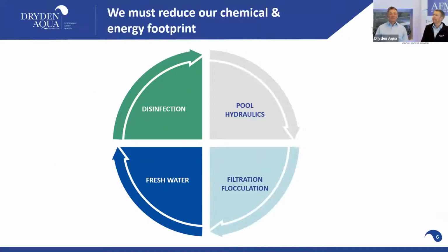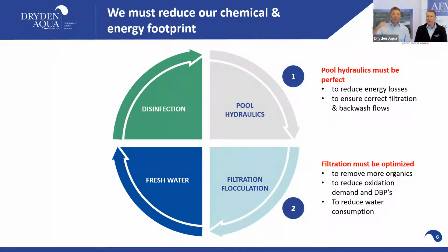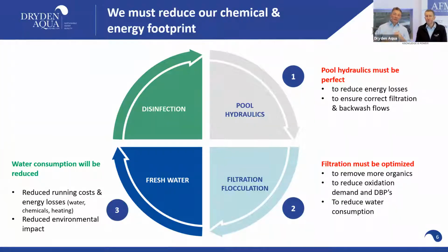So, who wants to talk about this? The 4. You tell me. 4 elements of pool water treatment. Number 1, the importance of pool hydraulics. We covered this in our first 3 sessions in detail. Remember how much turnover rate we have. We talked about the pipe dimensioning in the last one. And also in step number 2, we talked about filtration velocity, the importance of enough backwash speed, backwash velocity.